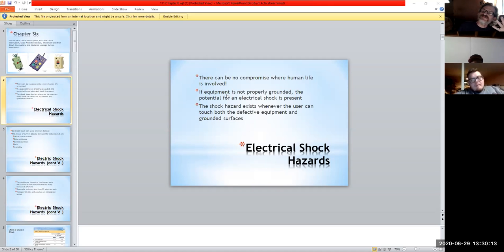Even though that time's still in seconds, seconds can be lethal, as far as how much electricity it takes to stop your heart or to start a fire. So that's one way to look at it. The GFCI is looking for that magical range of current imbalance, and it'll trip.